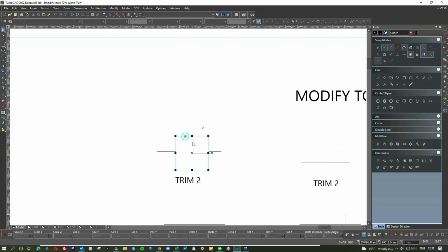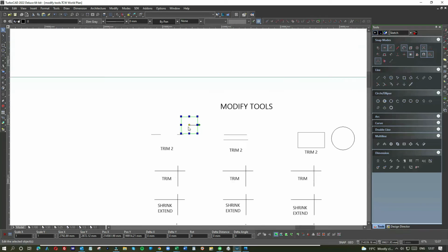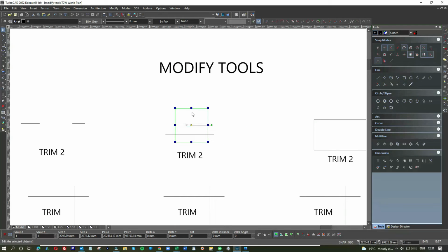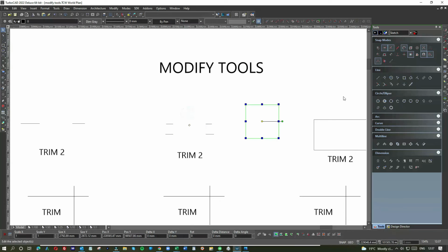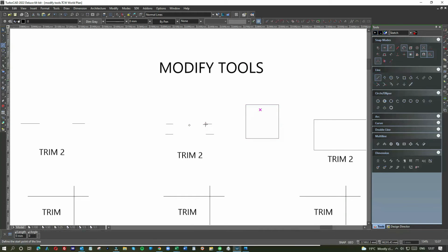Then deselect. And that was how I made holes. I used to draw full lines and then make holes in them. So for example, if I was putting a door in a wall, I'd come up with a square that was the appropriate size for the door, and then go to modify, object trim, select the rectangle or square, and that was how I was able to cut holes for doorways, etc. in walls.